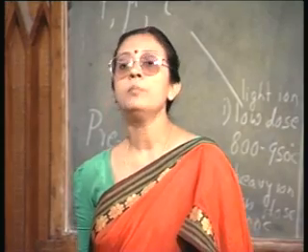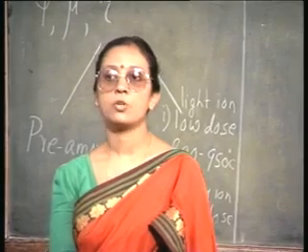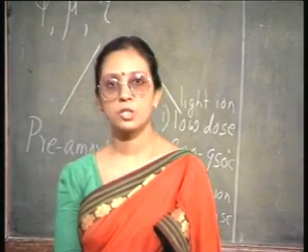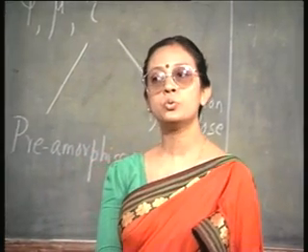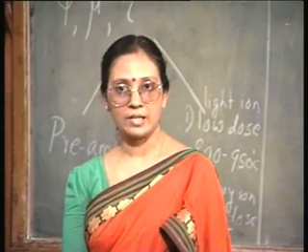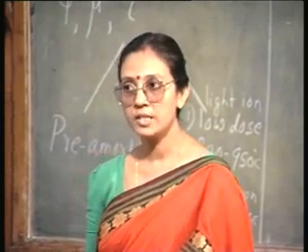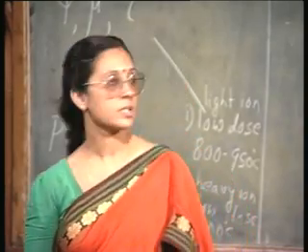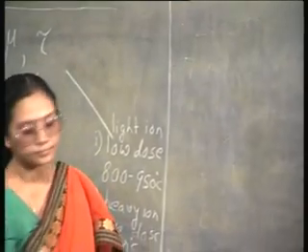Okay. So, what was the profile for the constant total impurity case? That is also a Gaussian profile. So, I have essentially two Gaussian profiles, and at the end of annealing, therefore, I can have a superposition of these two Gaussian profiles, which will work out to be something like